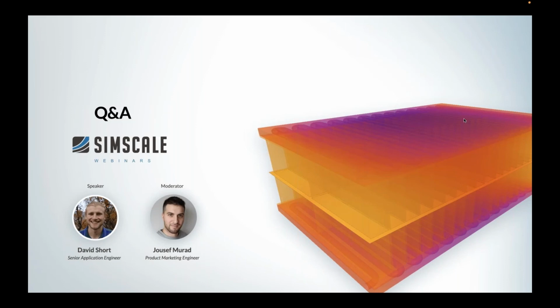I generally use automatic meshing about 80% of the time, but with any of our automatic algorithms or meshing strategies, you can add your own manual refinements on top of that. You can control the sizing manually as well. But generally, I find automatic meshing certainly does the job on the FEA side.